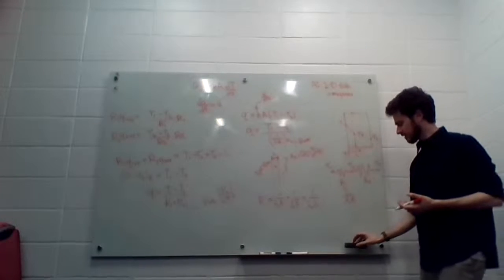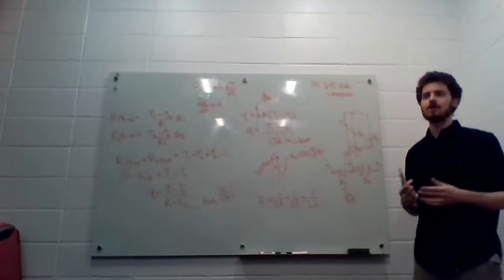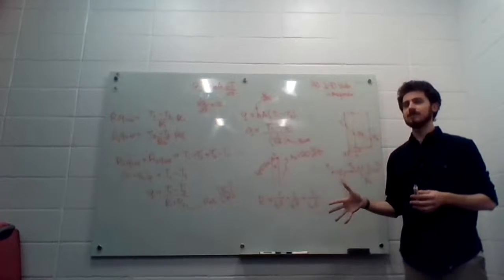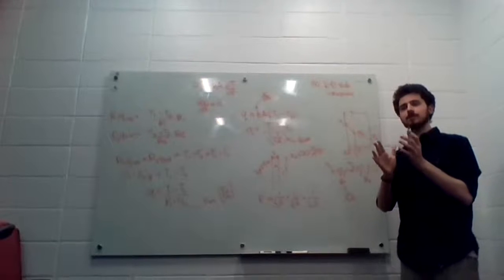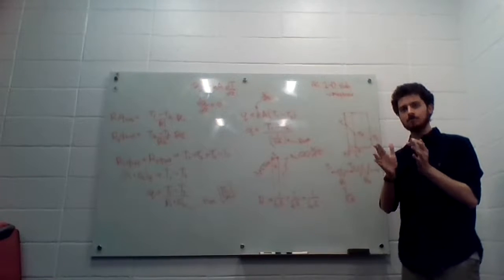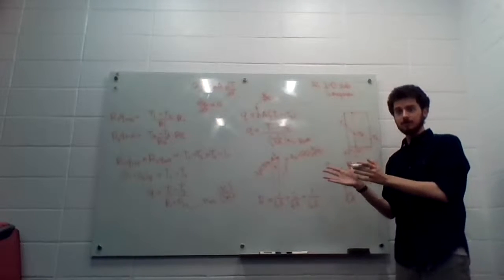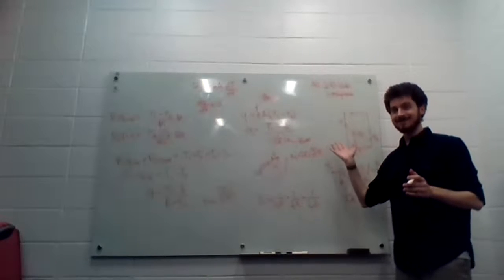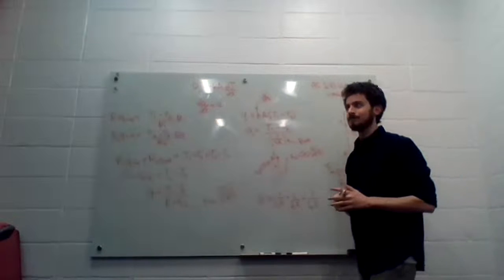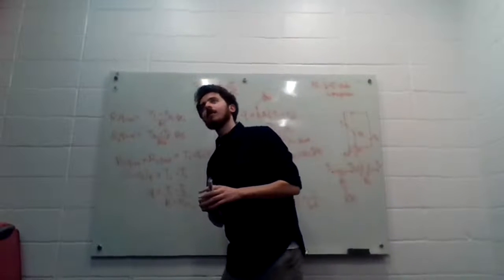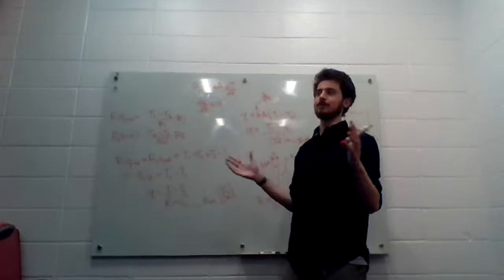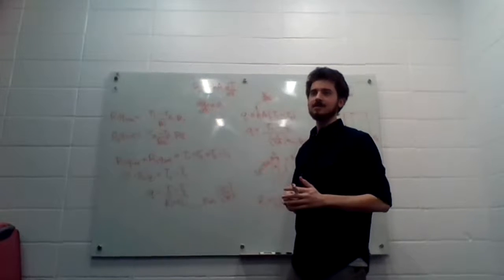Yeah, so thermal resistances are really useful because you can describe things with them. I'll just add that under extreme circumstances, the thermal properties of physical hard materials, solids, do change a little bit with temperature. Heat transfer coefficients change a lot. So we will say the external heat transfer coefficient is 20 watts per meter squared Kelvin and the temperature is 5 degrees Celsius.